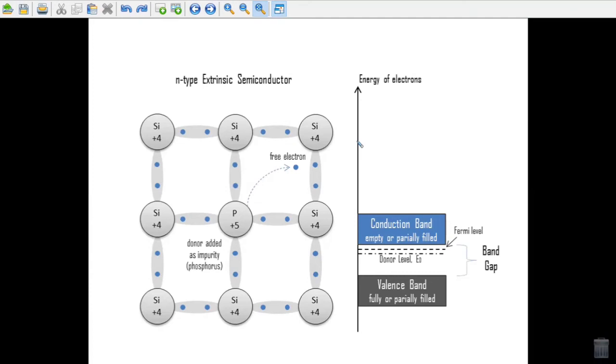The electronic properties of extrinsic semiconductors can be suitably described in terms of their energy band configurations plus certain intra-band energy levels introduced by the impurities, which are rather sparingly distributed throughout the host material. It is often more convenient, however, to consider the position of the Fermi level when discussing the electrical and other related properties of solids.